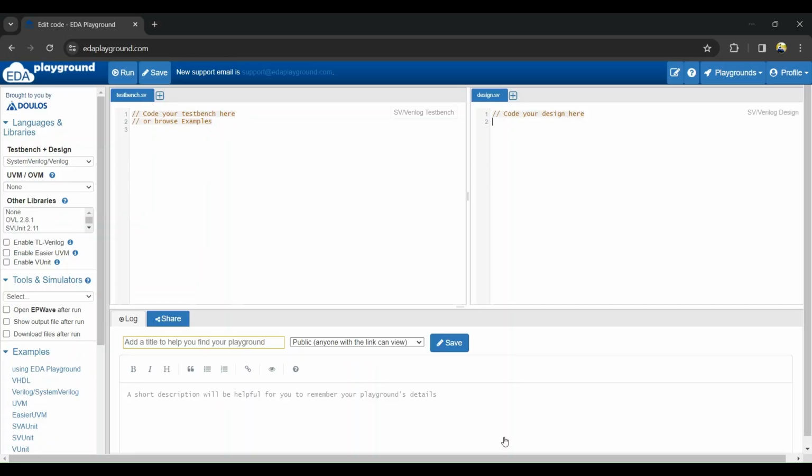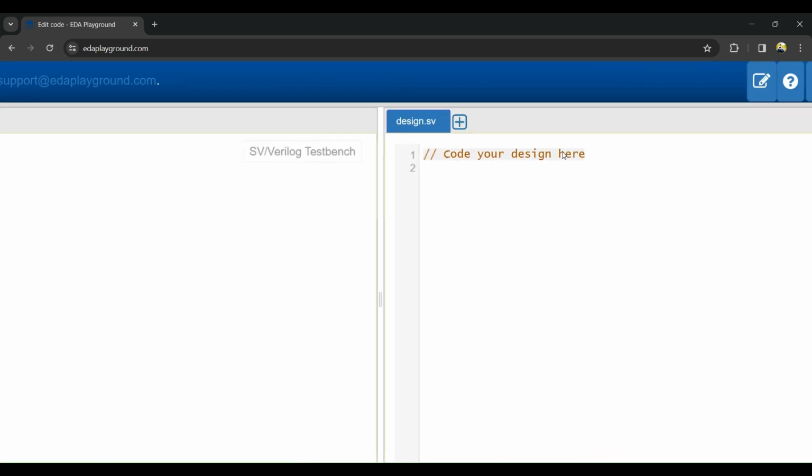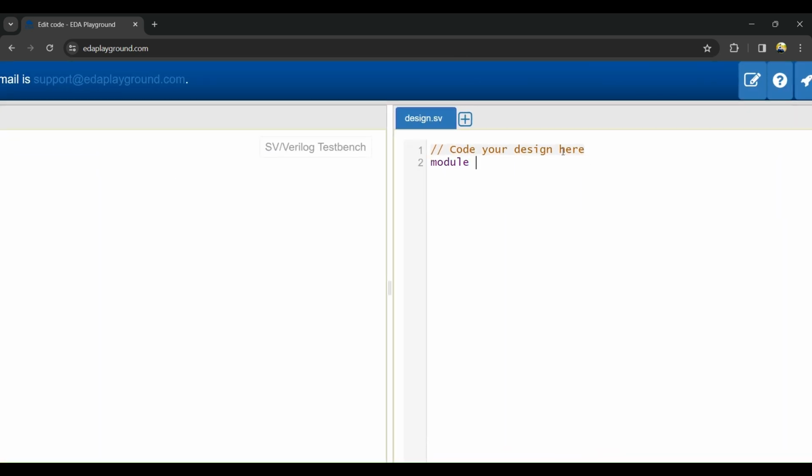Okay guys, now we will start making the Verilog code for the PISO. So I am giving the name PISO. Here I will take the input. We are designing the 4-bit shift register, right? So I am taking input [3:0] PI. PI is nothing but the parallel input: PI 0, PI 1, PI 2, PI 3. In this way, 4 locations will be allocated for the PI.